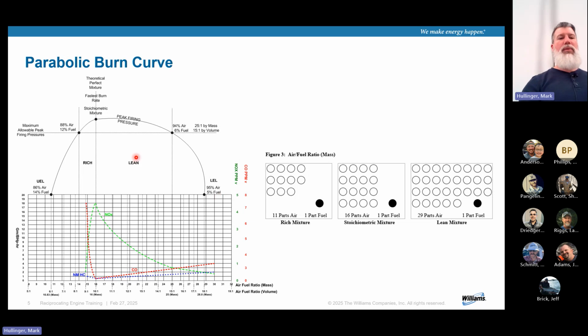So the Ingersoll Rands, the 4 strokes, they'll probably combust around this ratio over here. And a lot of the 2 strokes will combust around here in the lean area. And then when you have high pressure fuel injection, they're trying to lean out even more, and they'll combust somewhere around here. So it's simple, less fuel, more air. Less fuel means less of those 6 pollutants that we're trying to diminish that come out of the exhaust, okay?